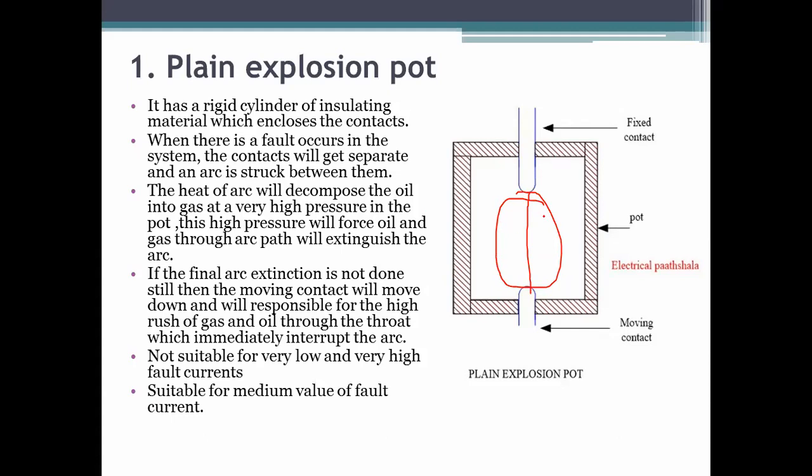So that gas and the oil, they will extinguish this arc. Means these particles get deionized there, and slowly your arc gets extinguished here. If the final arc extinction is still not done, then the moving contact will move down and will be responsible for the rush of gas and oil through the throat, which immediately interrupts the arc.